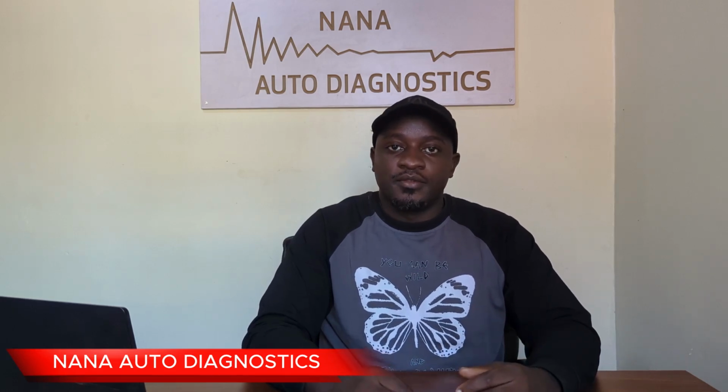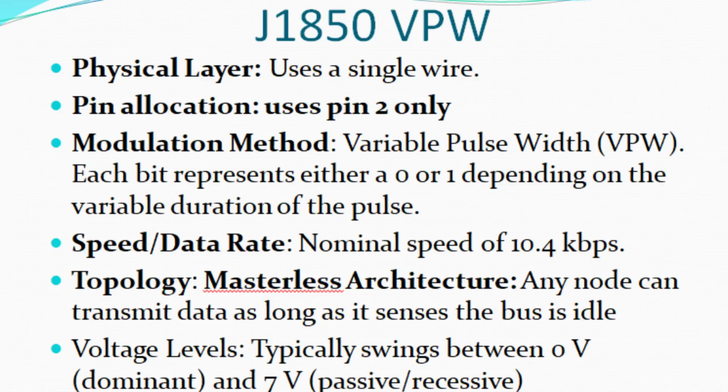So for the physical layer, the VPW uses a single wire, and this is allocated to pin 2 on the OBD2 port.